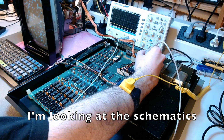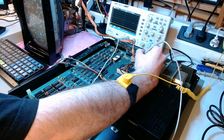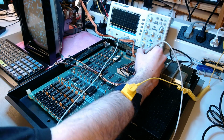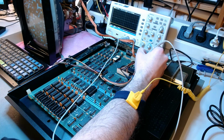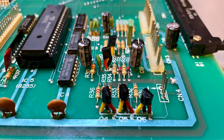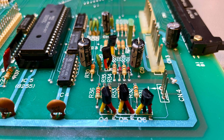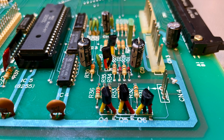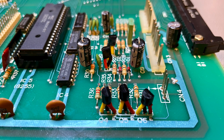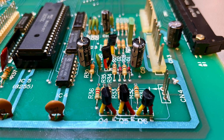And that comes from a transistor. Comes from the collector of one of these transistors here. I have to figure out which one. The transistor in question is one of the 5 transistors that I swapped out in one of the first episodes, as part of the restoration. And when I looked at it, I realized that I installed them with the emitter and the base swapped around.